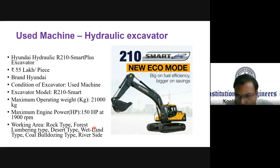See, you go for a hydraulic excavator manufactured by Hyundai, which is a used machine. They also have the R210 model. It's a used one, and the cost is going to be 55 lakh per unit. You see how this excavator looks. This also has a new economic mode with good control over fuel efficiency and good savings as well. The maximum operating weight is going to be 21,000 kilogram, and the maximum engine power is going to be 150 horsepower at 1900 RPM.